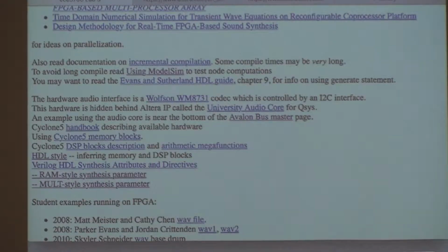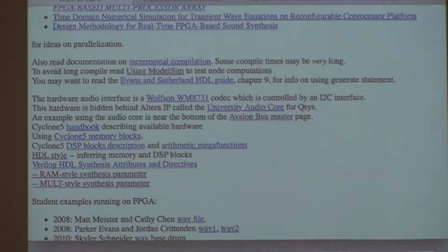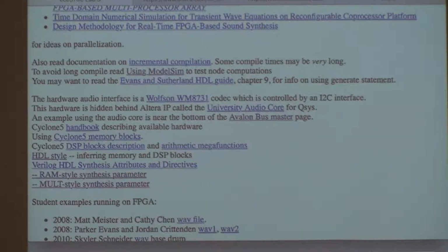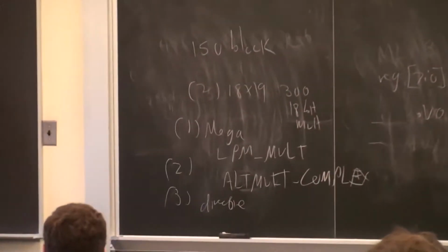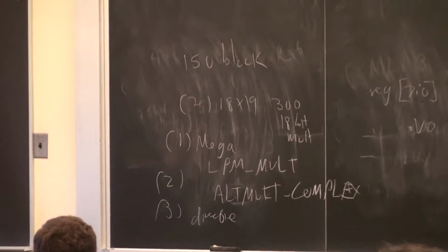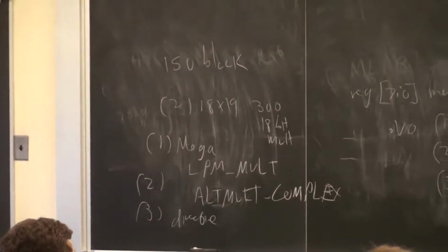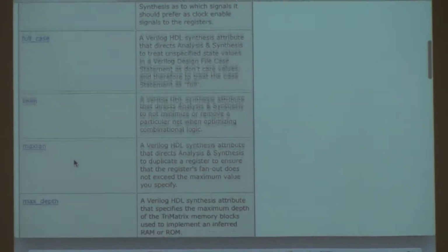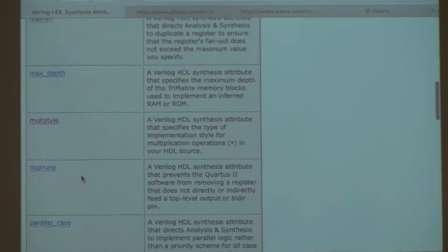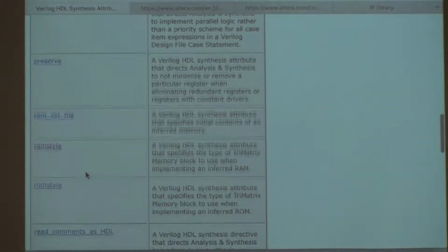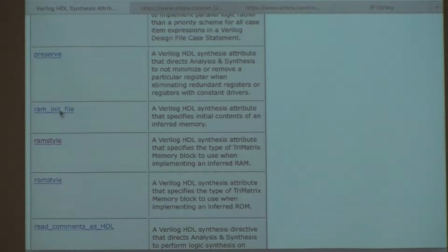So again, there's a synthesis directive for multipliers. In fact, there's a ton of directives. So I listed them all here. Most of them are of marginal usefulness. Though there is one other one I've used a lot, and that's RAM init file.